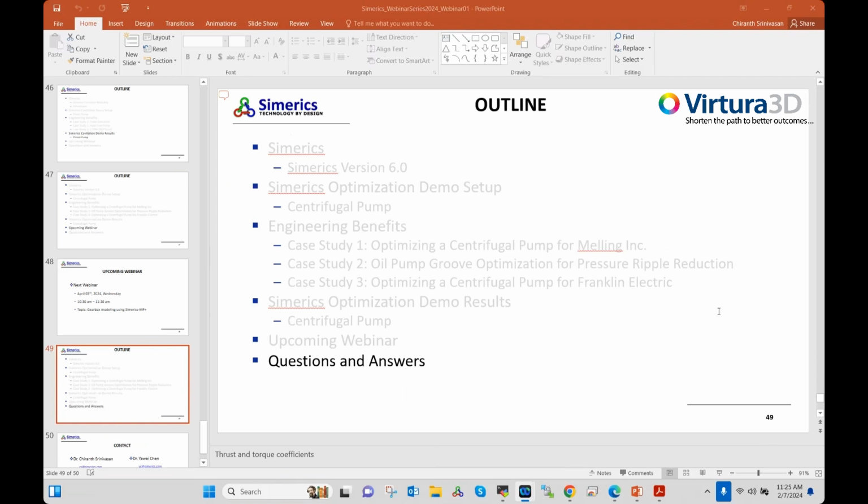The second part of the answer is that we also have an erosion model, which uses some of these terms to model the removal of solid material, essentially the changing of the fluid space. That model is something new. We are still developing things in that, but both of these together can help us predict the erosion intensity. If there is interest, we can definitely send you some material.